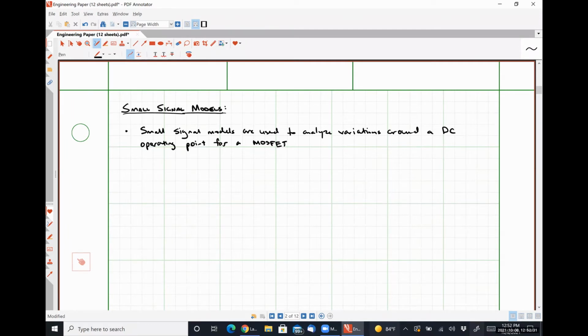So our current voltage relationship, whether we're in the triode region or the saturation region for our MOSFET, is what's called a nonlinear relationship, right? For a resistor, the resistance is simply the constant of proportionality between the voltage and current, okay? For a capacitor, it's not that simple. There's a derivative-based relationship or an integral relationship, depending on if we're converting voltage to current or current to voltage, and the same relationships hold for the inductor, just inverted. We covered all of that back in Circuits 1.